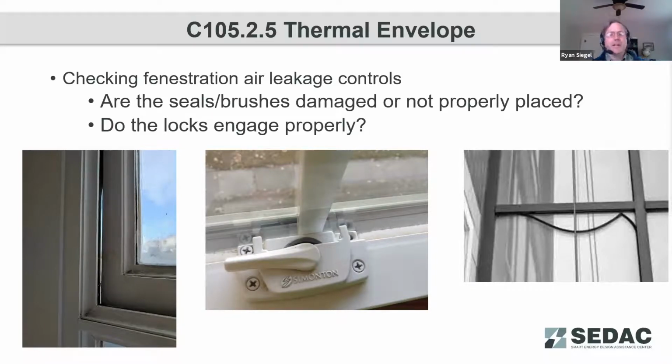So understanding that. And on the right here, we show one of the benefits of doing a pressure test on the building: seals that may not have been quite fully seated during an envelope pressure test. Those seals might pop out of place and present themselves as saying, "Hey, I wasn't installed properly.